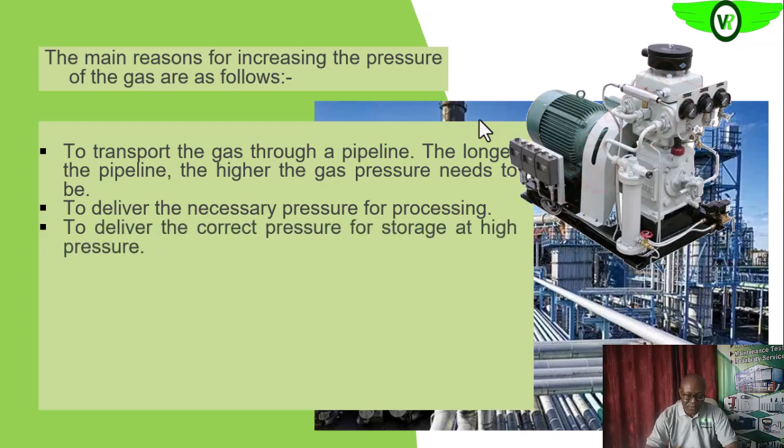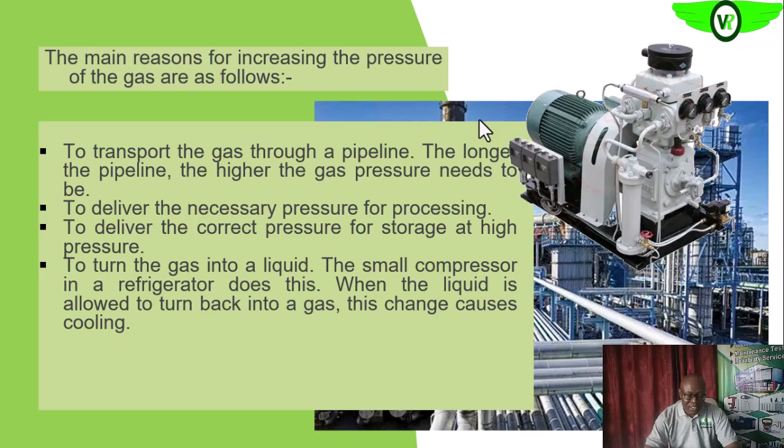Thirdly, to deliver the correct pressure for storage when we want to store the compressed gas. For us to have it in the liquefied form, we have to compress it to a level, like in LPG. We have to compress it to a level for it to remain in that liquefied form, so that we can conveniently store it in vessels.